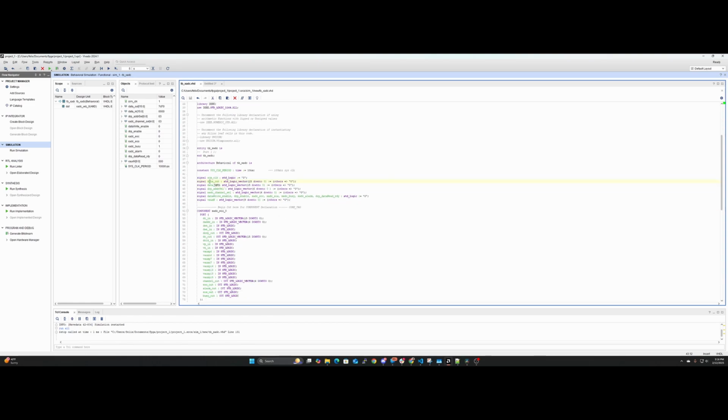For example, the data out, the data in, the address select, the channel out of the XADC, data write enable, the DRP enable, and a conversion and a sequence, busy, alarm, and DRP data ready. We all initialize the value to 0 and the V auxiliary to 0.